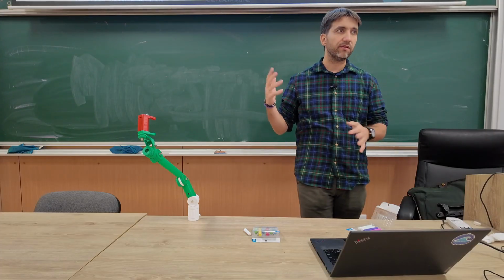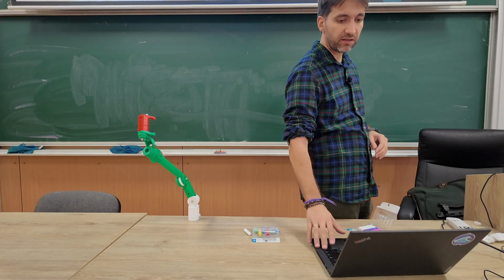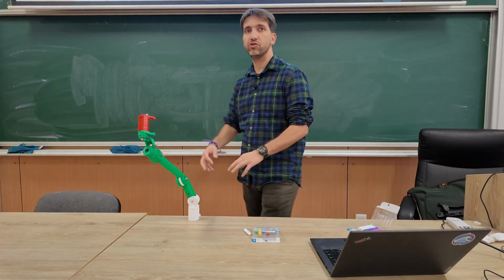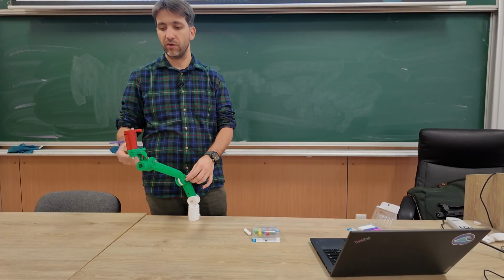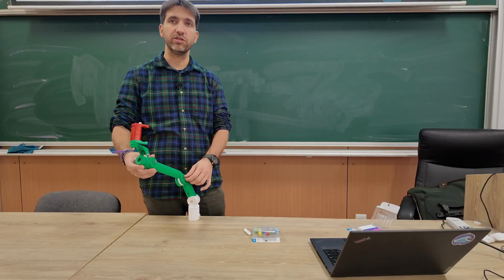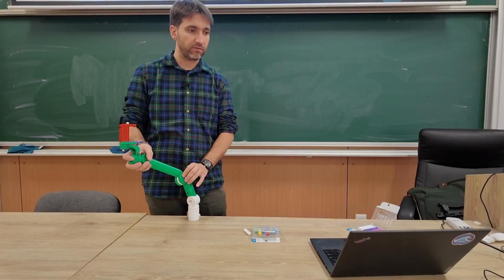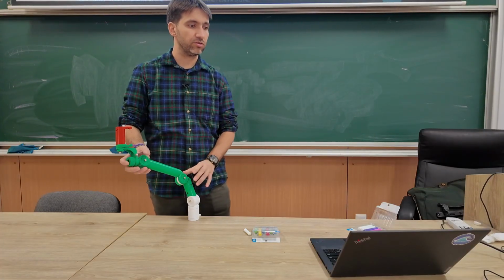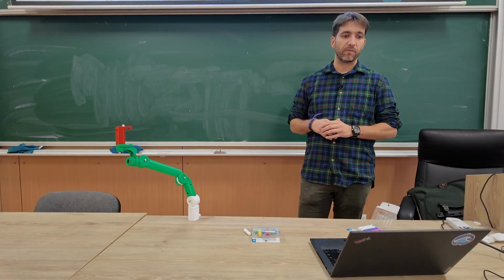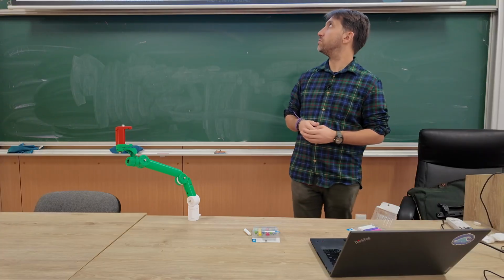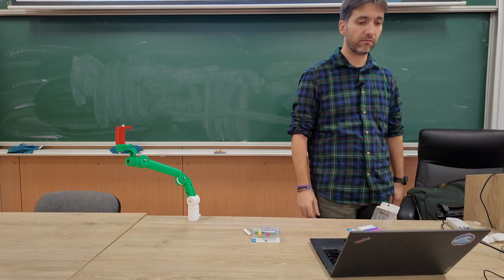So we saw different ideas we had here of what the set point and the response can be, right? We said it can be joint positions, joint velocities, right? But in the end, what do I want to control? Do I care about controlling the joint positions itself? I care about the end effector, right? So can I have a set point as being the end effector pose and the response being the measurement of the pose? Basically, these two things have to be the same quantity, the same physical measurement.